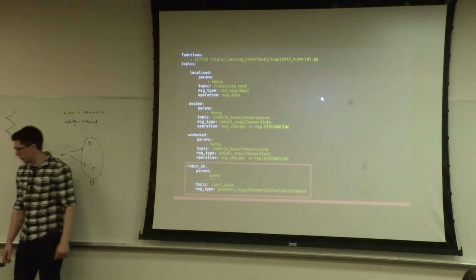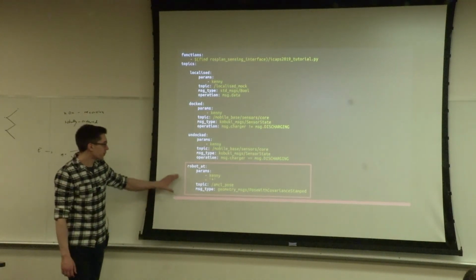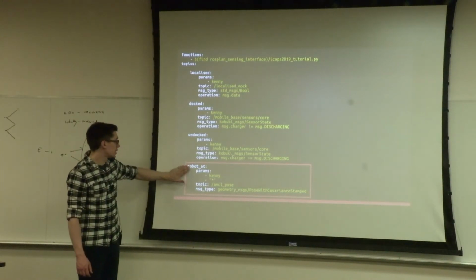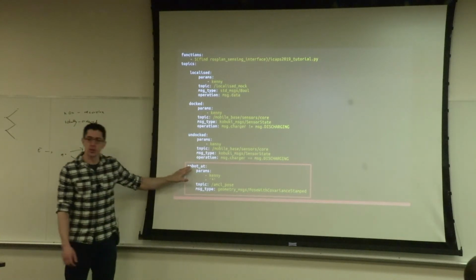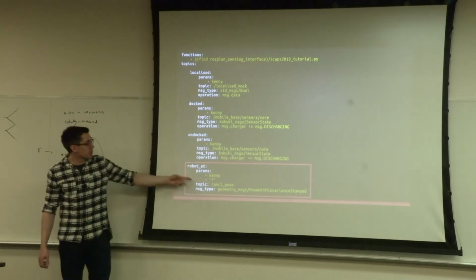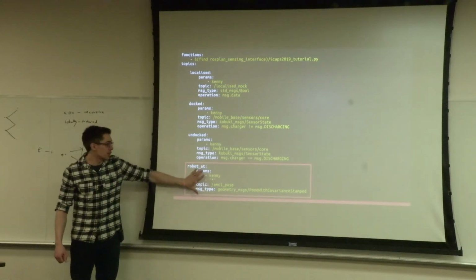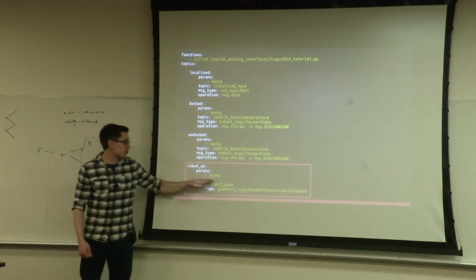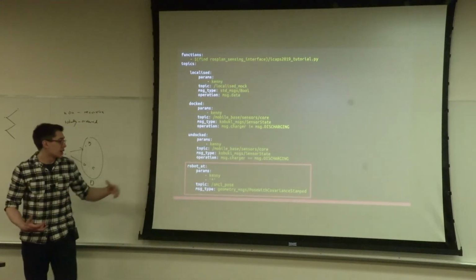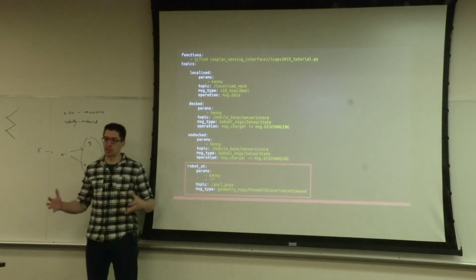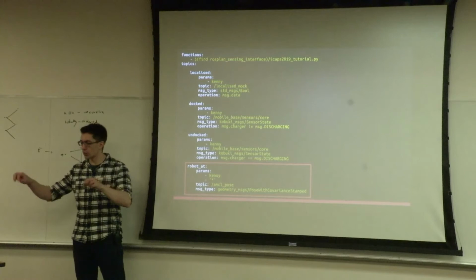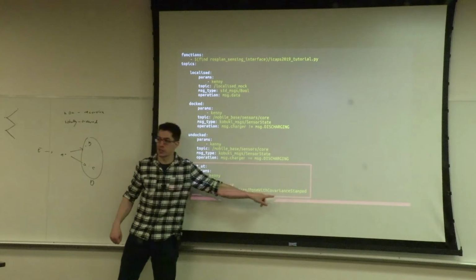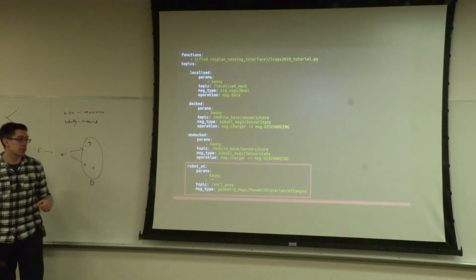Okay, let's take a look at this one. A bit more complex. So again, I'm interested in robot at proposition. And in the sensor interface, you can link one predicate name to actually a number of propositions by adding wildcards into the parameters. So this block here is only interested in robot at with the first parameter Kenny, but the second parameter could be anything. The topic is the AMCL pose. That's those green arrows again. It's publishing an array of coordinates and orientations. And the message type for those is pose with covariance stamped. Stamped just means time stamped, essentially.